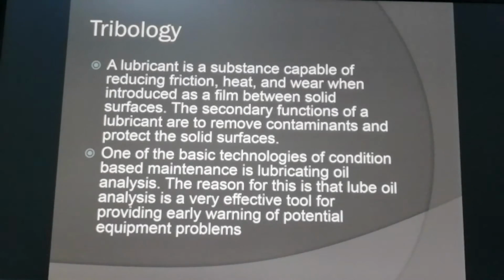Tribology. A lubricant is a substance capable of reducing friction, heat, and wear when introduced as a film between solid surfaces. The secondary functions of a lubricant are to remove contaminants and protect the solid surfaces. One of the basic technologies of condition-based maintenance is lubricating oil analysis. The reason for this is that lube oil analysis is a very effective tool for providing early warning of potential equipment problems.